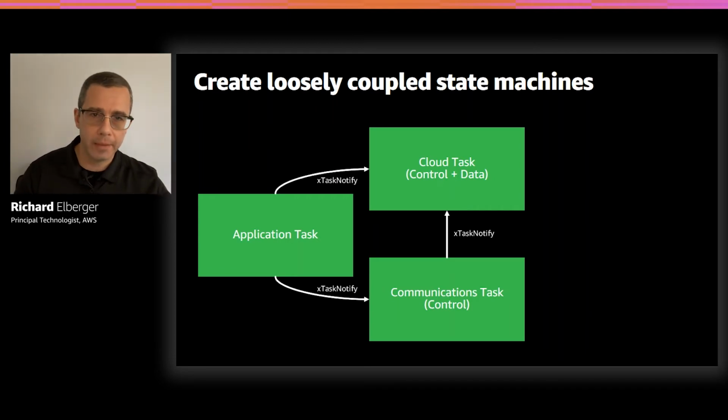Effectively, this is the MQTT client. The MQTT task knows a lot about MQTT, but it doesn't know anything about sockets or about the communications module. It doesn't care. It shouldn't care. What it does care about is how to handle MQTT from input and output perspectives. So it needs a clean interface for how it can deliver payloads to the communication task.